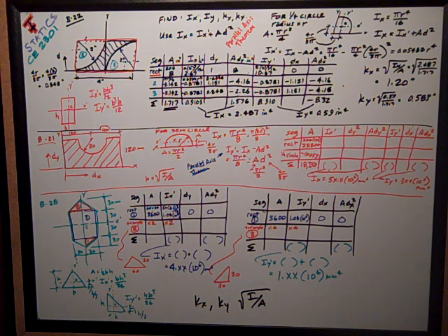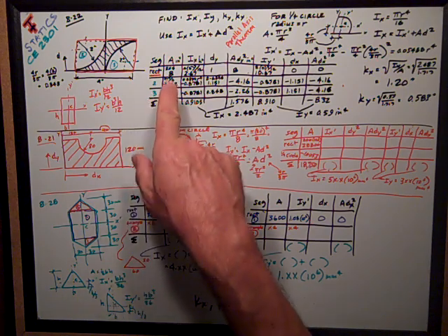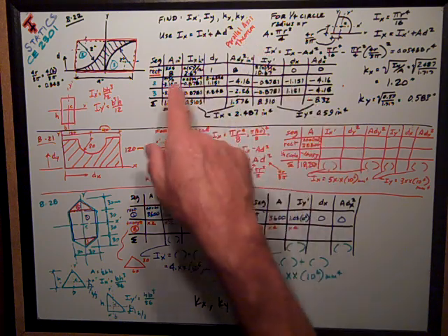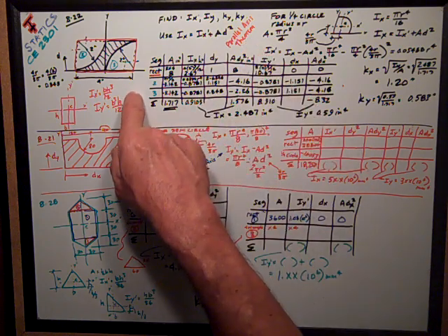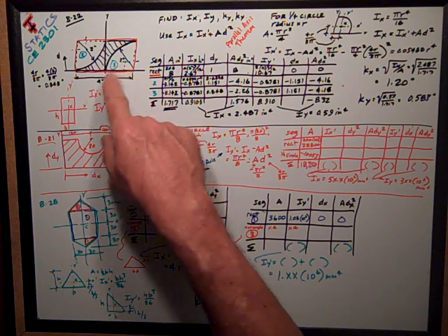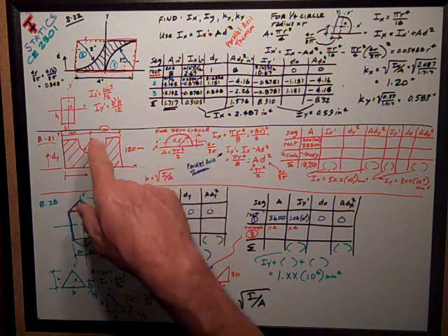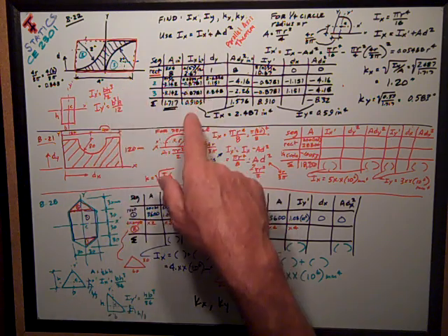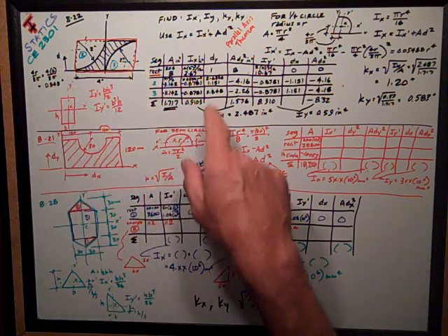And so, similar to what we did on that last homework, we're going to use the parallel axis theorem a lot, but we're going to solve backwards for the properties of the quarter circles, their areas and moments of inertia, especially about their own centroids.